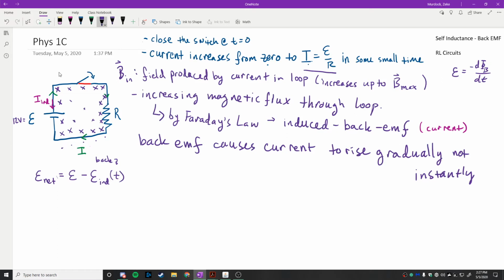And we find out that there's actually something that matters in terms of this process of turning on the circuit, right? And in the case of motors, it becomes a little more complicated, but the biggest thing to understand is that when you do have a motor that's running, there's always going to be a back EMF, and the back EMF may actually be proportional to how fast the motor is spinning. Did you guys follow that?